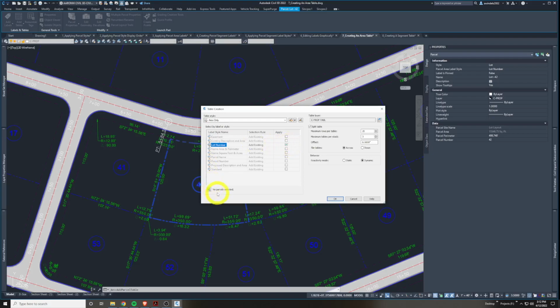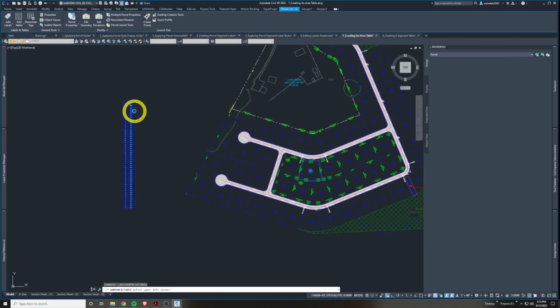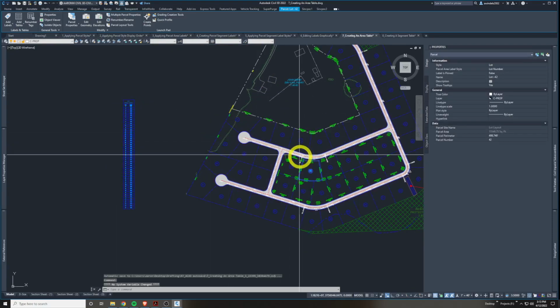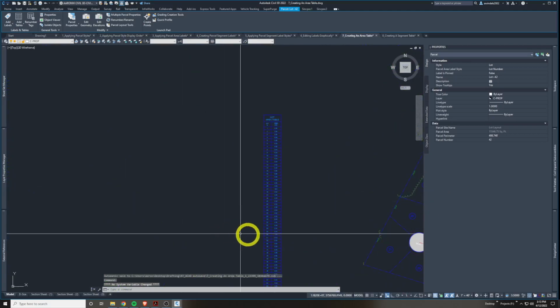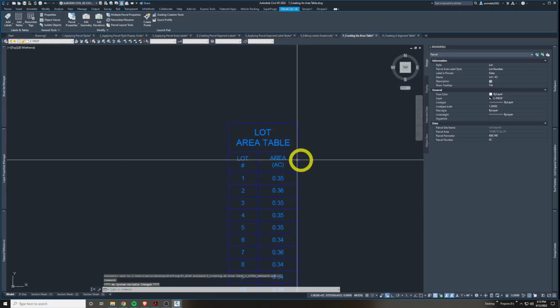Checkbox that. You can select them manually with this as well if you're having trouble picking which style of the parcels you want it to label. This is just more advanced to segregate them. For this, I'm going to say 60 rows because I know there's a lot of them. Let's hit OK. We'll make a column over here somewhere of all these parcels 1 through, what is it, 53? Made them all with their little areas and acreage.